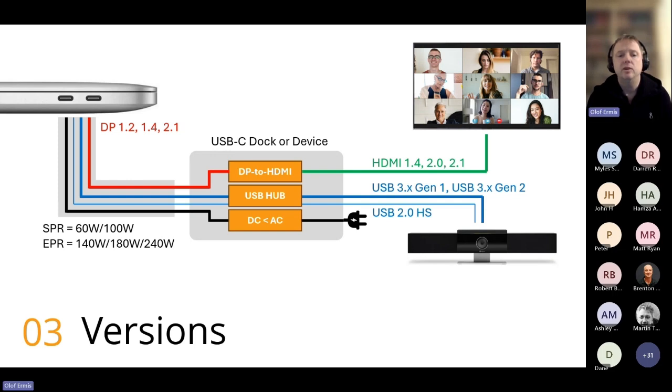And here it's good to note that when we talk about USB 2 and USB 3, they are basically 100% different protocols. So even if the hub that you have in between is a USB 3 hub, you can say it is one USB 2 hub and one USB 3 hub put in a single product. So you always talk USB 3 from a laptop to a device, and you talk USB 2 from a laptop to a device; you never go USB 2 halfway to the hub and then change to USB 3, or the other way around.